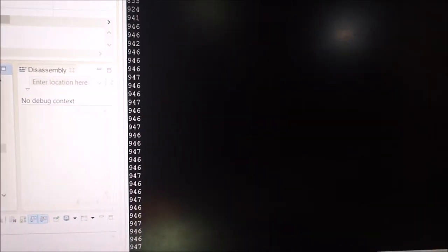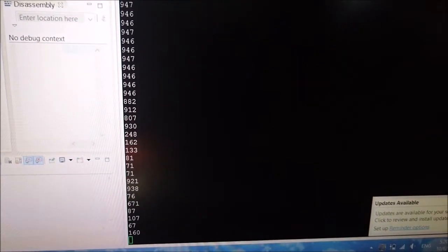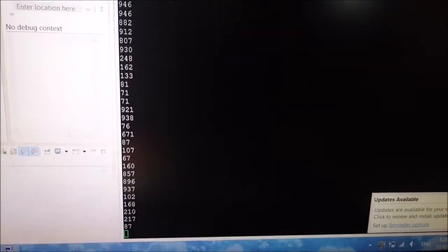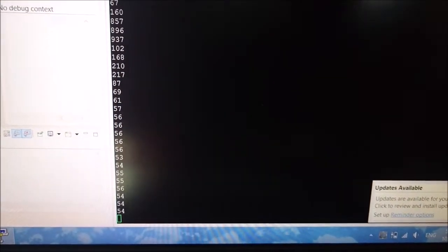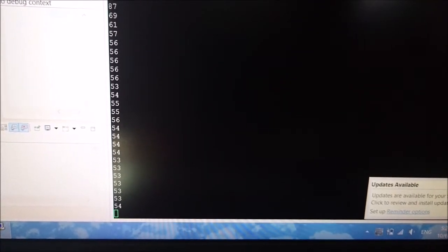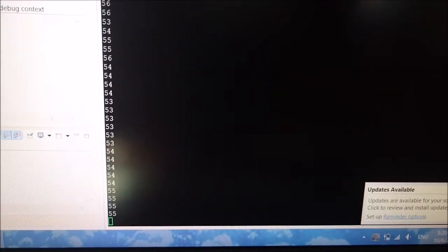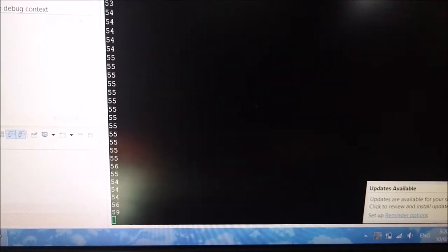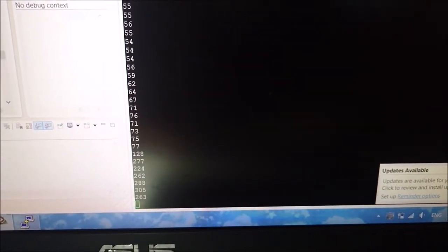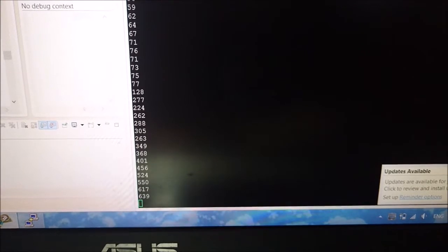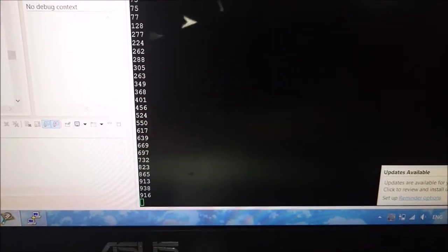Then I will use the flashlight, getting closer to it, and you can see that the value is not so constant, but let's change a bit on the view. Okay, now we are getting a constant of 50 plus, which is a very small value, when it's at very high light intensity. Now I will slowly remove it, moving the flashlight further and further away, and you will see that the values are increasing. And now it's back to 900 plus, around that.